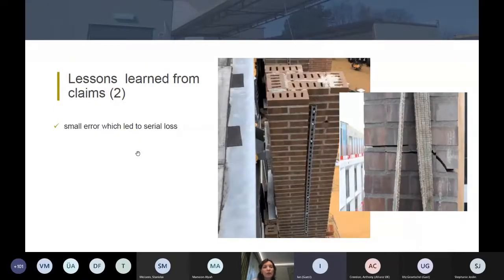The second example here is a hotel facade. It was formed out of prefabricated brick elements that were glued together in a factory and hung from the top of the site. There were something around 60 prefabricated elements, and when a third of this quantity was already installed, there were cracks on the lining, and there were different possibilities for how to manage this.